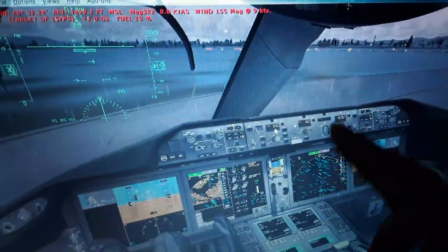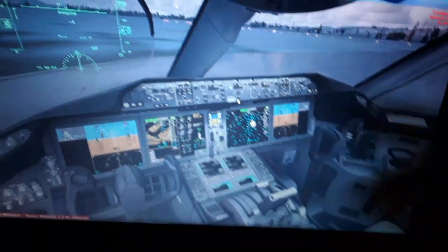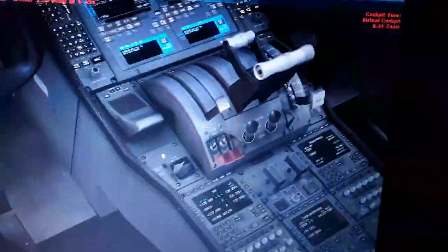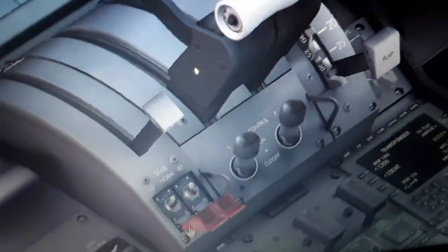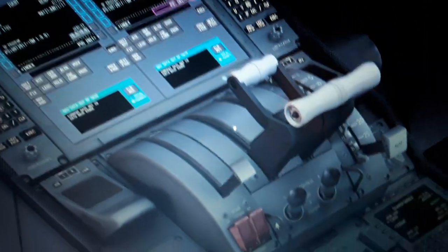We can lose the auto trim function from the autopilot flight director system panel, and the auto throttle, and also from the flight management computer inputs for the flight control computers. This is for all Boeing 737, 747, 757, 767, 777 and 787 aircraft, for Boeing aircraft nearly.